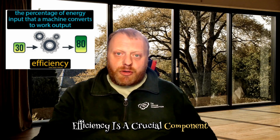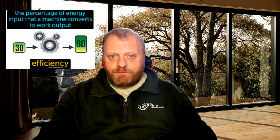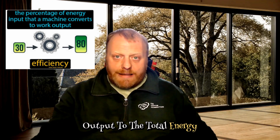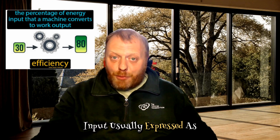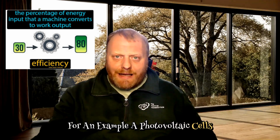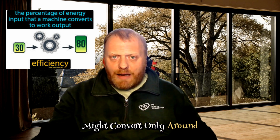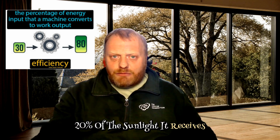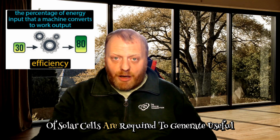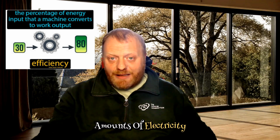Efficiency is a crucial component in BSE. This is the ratio of useful energy output to the total energy input, usually expressed as a percentage. For example, a photovoltaic cell might convert only around 20% of the sunlight it receives into electrical energy. The rest is lost as heat. This low efficiency means large areas of solar cells are required to generate useful amounts of electricity for a building.